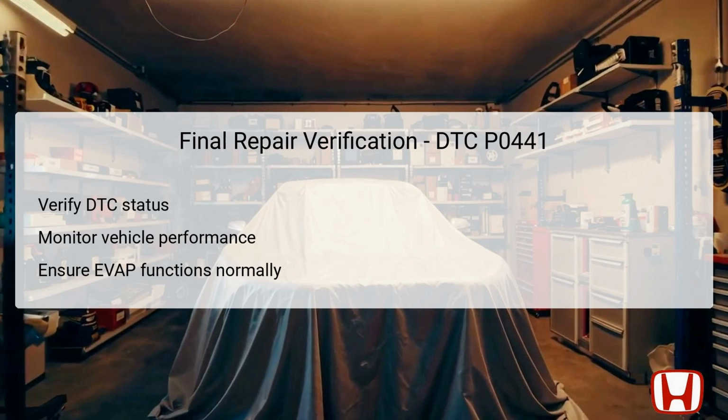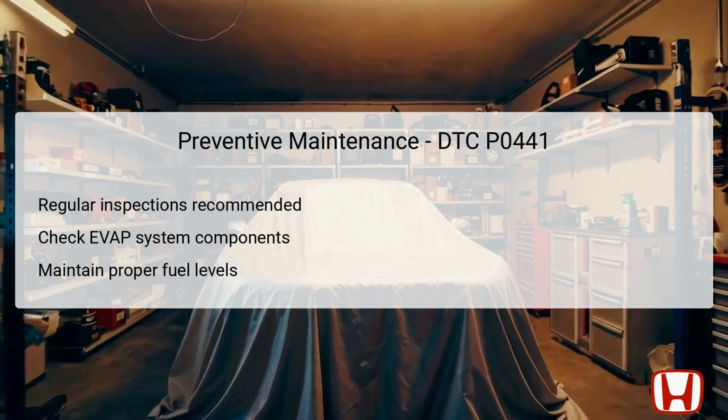Regular inspections and preventive maintenance are crucial in managing the health of the EVAP system in your Honda Accord. It's advisable to perform routine checks of all related components, including the EVAP canister, purge valve, and lines for any signs of wear, damage, or blockages.